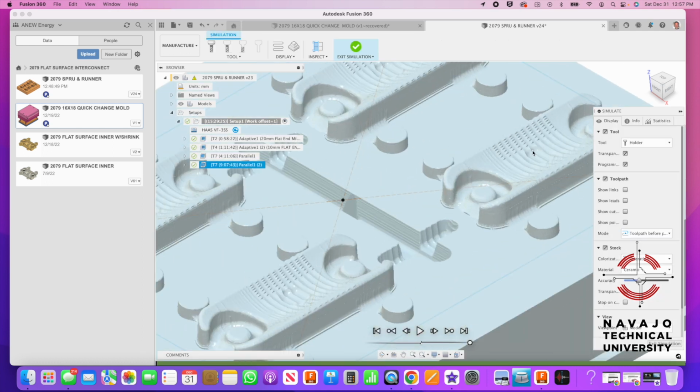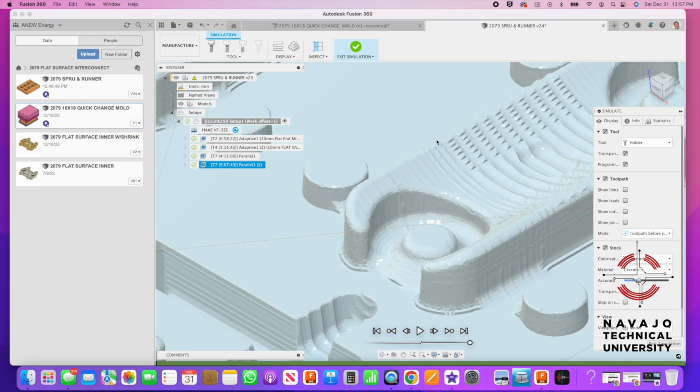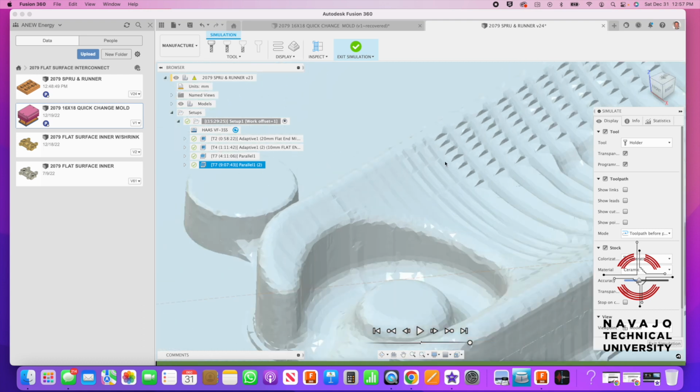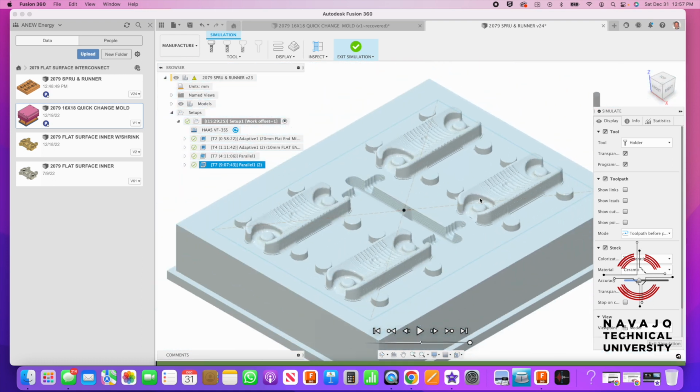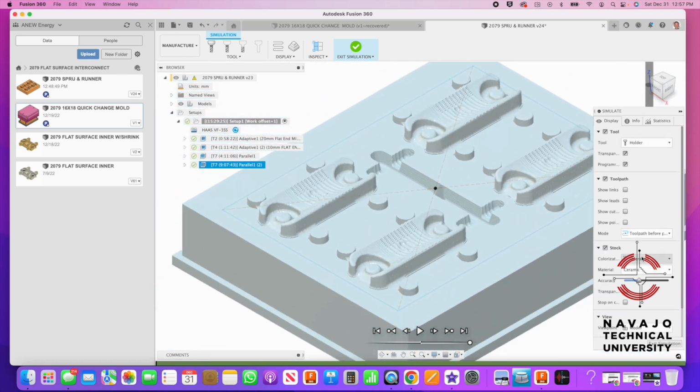So we had all this rough stuff that it was kind of stepping over, and it was really rough. These are some of the end cutters of the flat end mill, but this is the ball end mill, stepping over big 5 millimeter steps to rough it out. So now we're going to get tighter, and we're going to really get going. So I'm going to hit play and watch this routine run. All right, here we go.